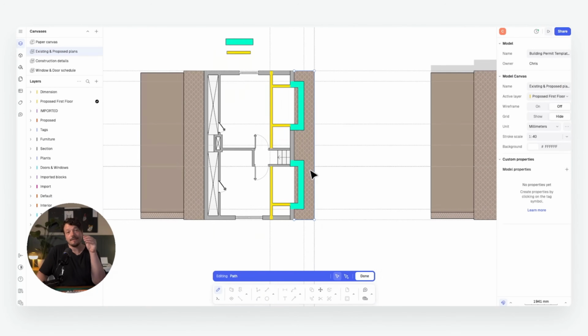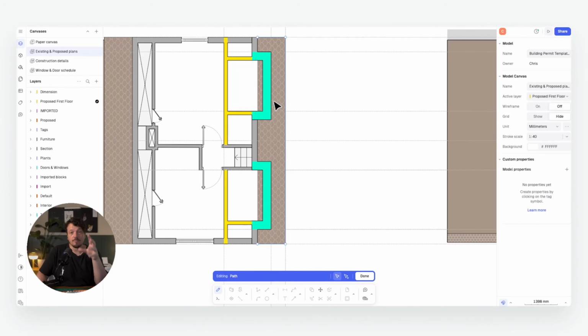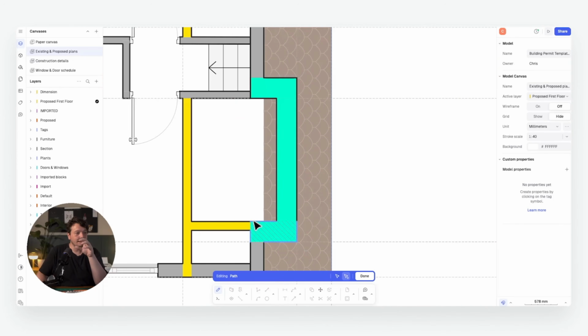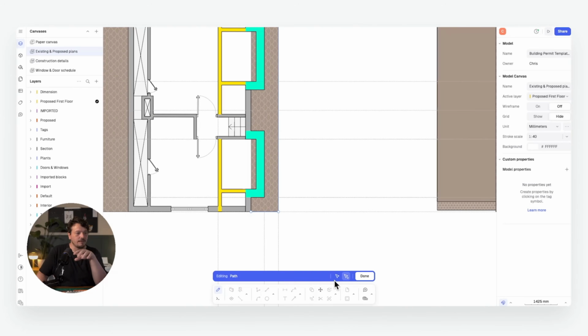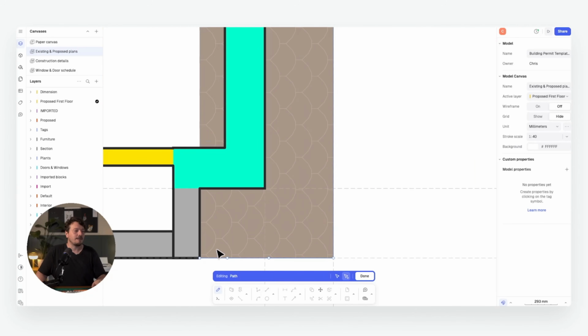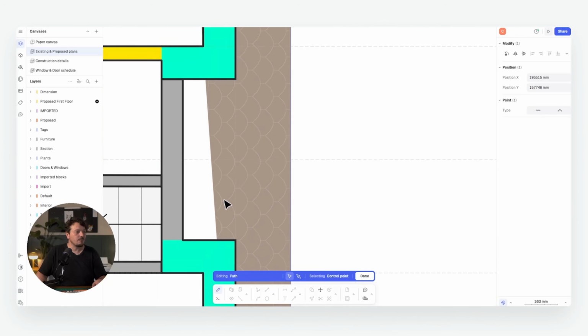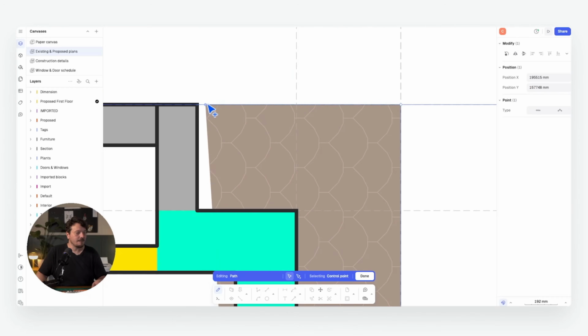And you can see here that the rectangle that's formed the visible roof edge now needs to be adjusted. So one really helpful thing is that you can add points to the path. So having just double clicked on that, I can add points to this line, and that means I can take it around those corners as I need to.